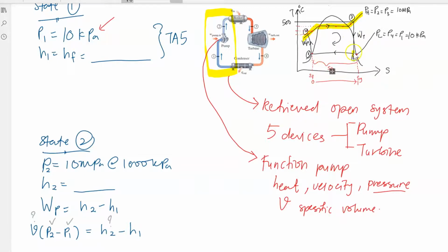So going out from the turbine, you have some in vapor state, some in liquid state, until the condenser releases all the heat, and now the steam becomes liquid, right? So for H1, you can directly read from table A5, at saturated liquid conditions over here. Okay, so we do have your H1, right?